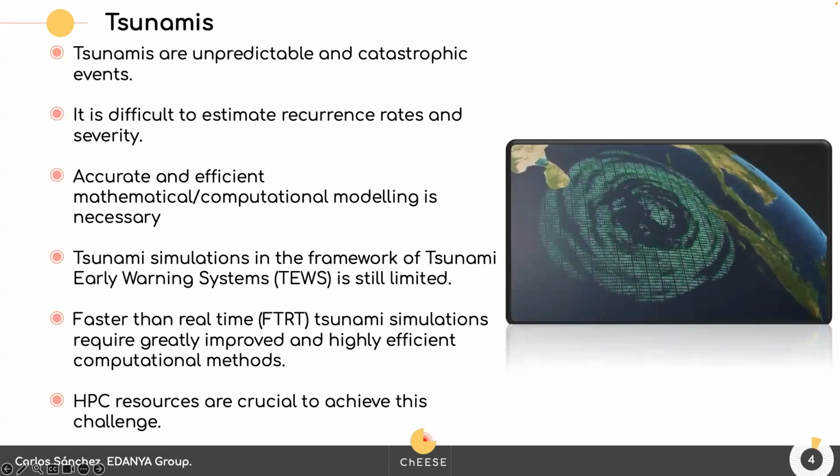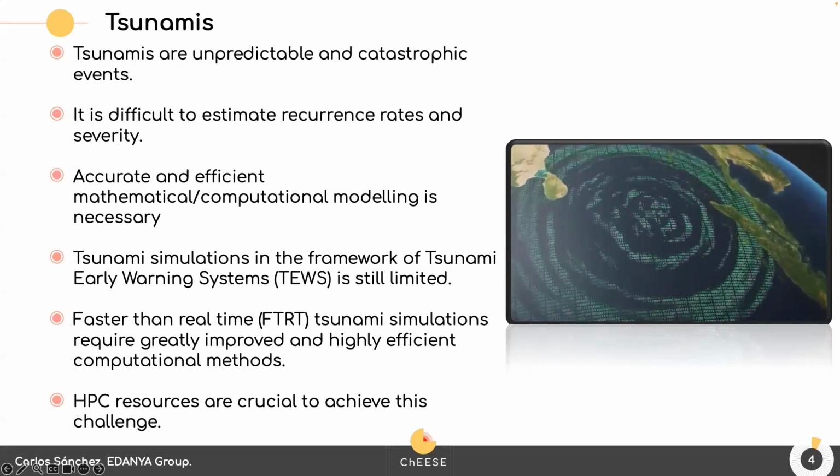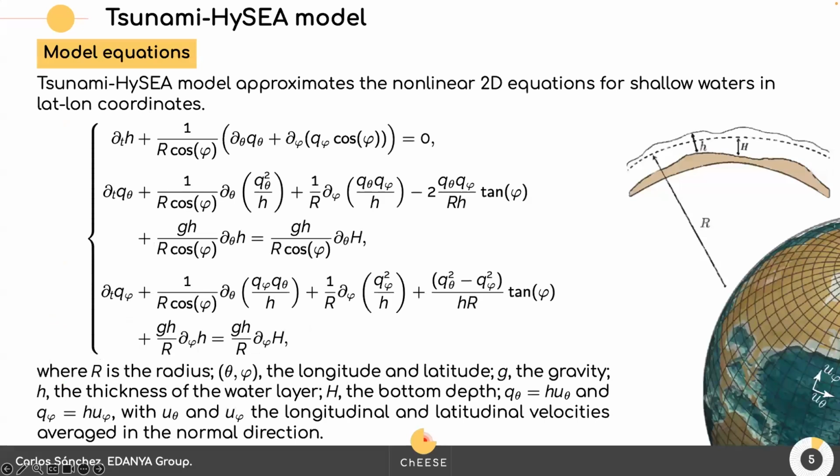So it is very important to use HPC resources to achieve this challenge. Here we can introduce the Tsunami-HySEA model, which approximates the non-linear 2D shallow water equations, in this case in longitude and latitude coordinates.